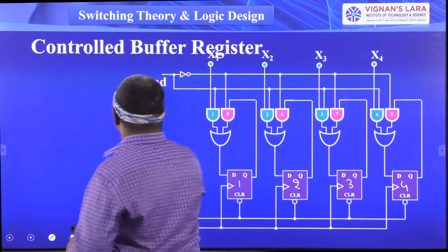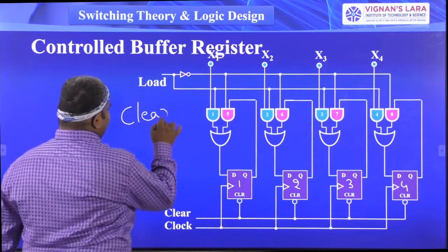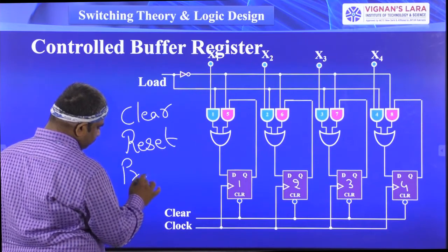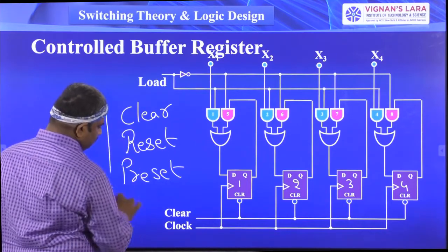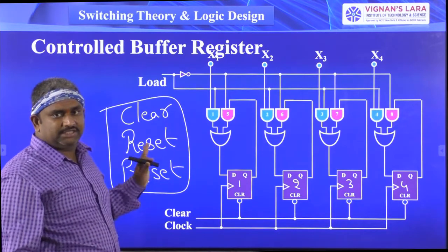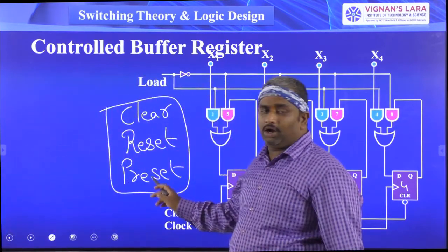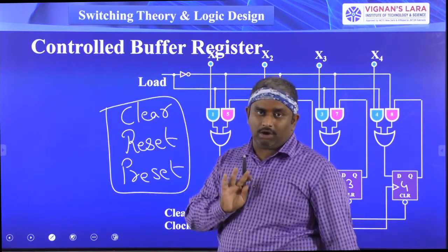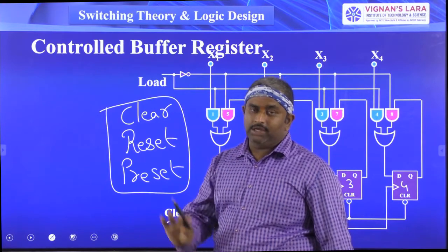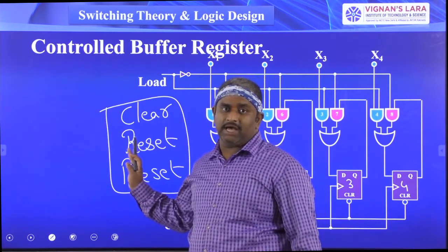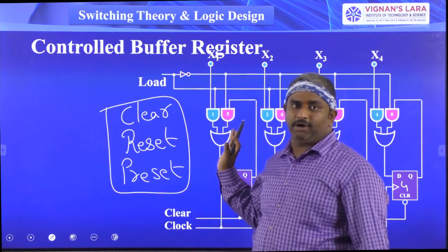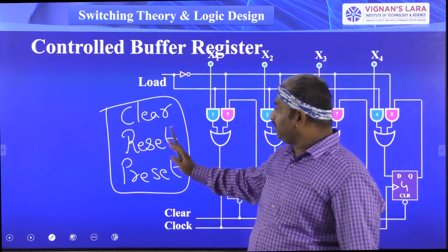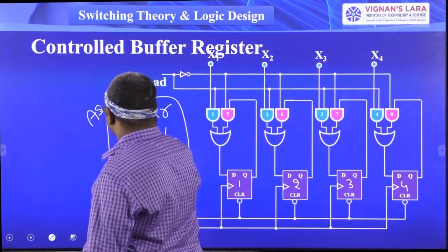So here I am writing again. Clear, reset, preset, right? These three signals are called asynchronous inputs. These asynchronous inputs are independent of the other inputs. There is no relation with the load and clock signal. Okay, these three are the asynchronous signals.